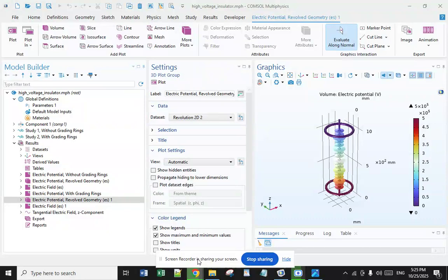One of the main advantages of suspension insulators is their flexibility. As they are suspended, they can move to absorb dynamic loads caused by wind or conductor oscillations, reducing the risk of fatigue and failure. In addition, their modular design allows easy replacement of individual discs without the need to replace the entire assembly, facilitating maintenance and reducing operating costs.